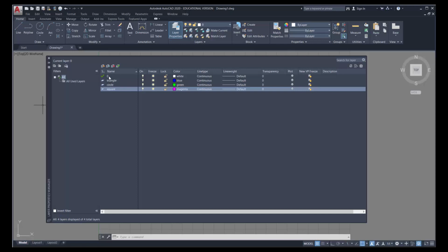But by having that layer, whenever I'm importing another drawing and I want to control where the elements of that drawing are going to go in reference to the layers, I basically take the other drawing and turn all the elements to layer 0 and then import it into here. And from here, I then switch its layer property. We'll get a chance to do that later on. So everything's good here. I can select any of these layers and change the one I'm going to draw in, but for now just leave it as is and click on the X.